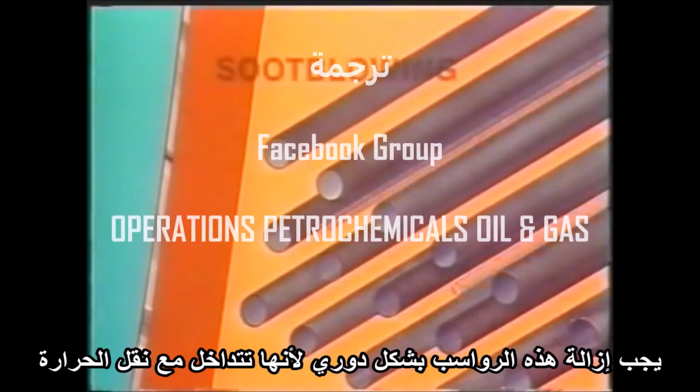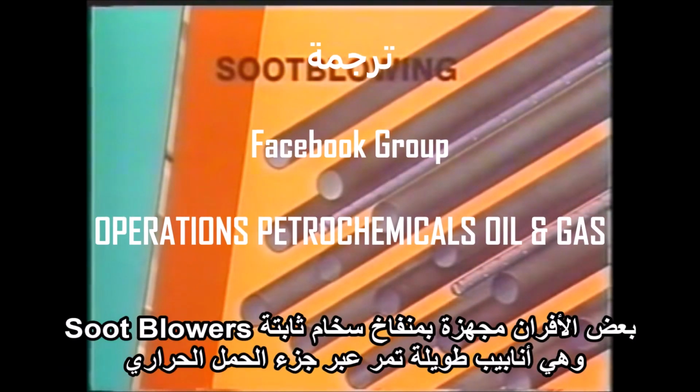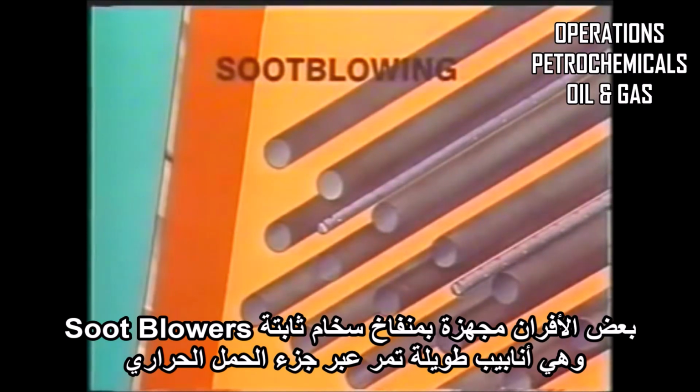In furnaces which burn oil, an ash deposit or soot gradually accumulates on the outside of the convection tubes. These deposits must periodically be removed because they interfere with heat transfer. Some furnaces are equipped with stationary soot blowers, which are long tubes that run through the convection section. Steam is circulated through holes in the soot blower to blow off any accumulations of soot.